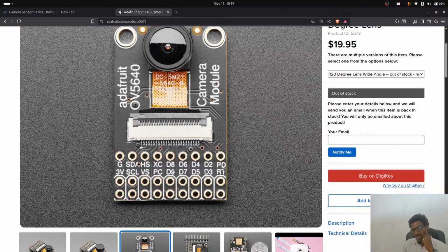And then next to them, we see there's a power down and a reset button, but those are just sensor specific. They're not really control signals. But what I want you to notice here is that there's a D2 all the way to D9, which is, I think, 8. 1, 2, 3, 4, 5, 6, 7, 8. Yeah, which is 8 signals. So there's 8 lines of data going through. And this is what we refer to as the data interface. And then the SDA and the SCL are going to be the control interface.